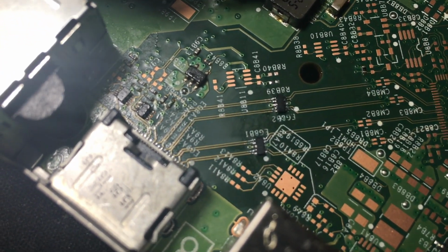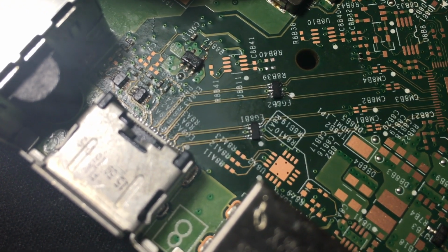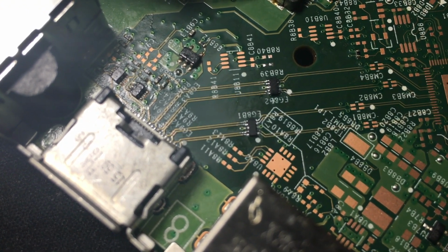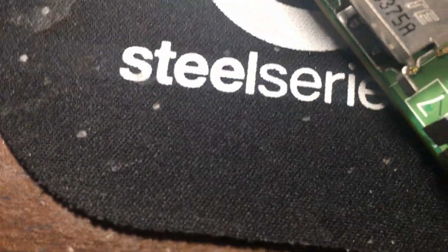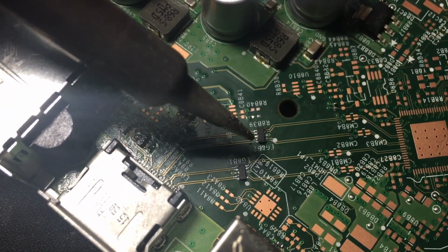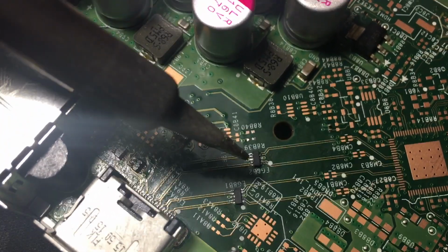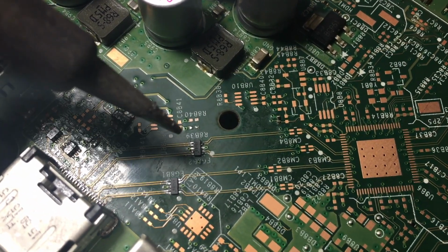But as a result of that, you have to clean it up, check the pins. So you wind up having to run it across a few times, unless you get lucky and the solder sticks for you really easily. I can't stress enough how, so I'm trying to look into this, the soldering iron barely fits in there. So you've got to be careful, you don't want the chip to move, you want to keep the chip centered, so you can't apply too much pressure.